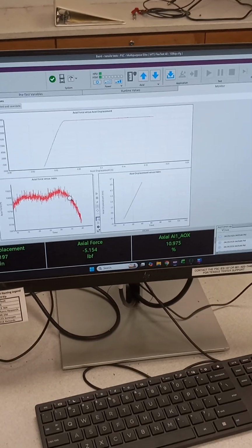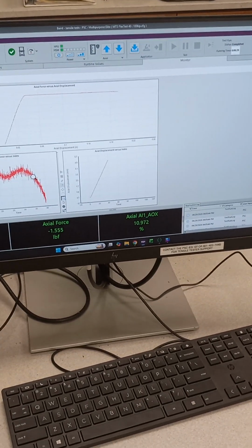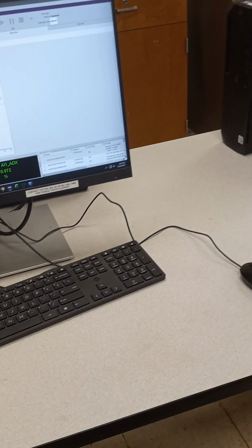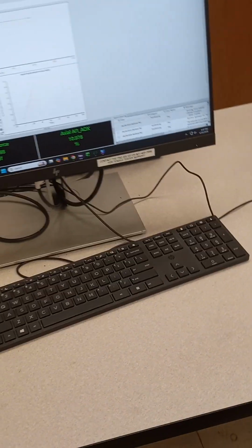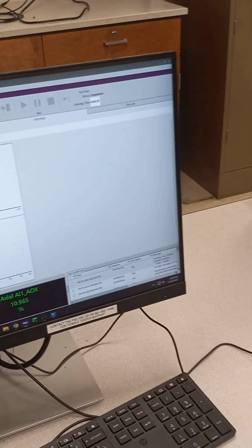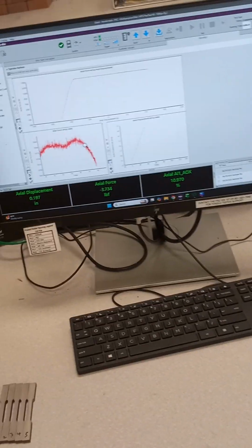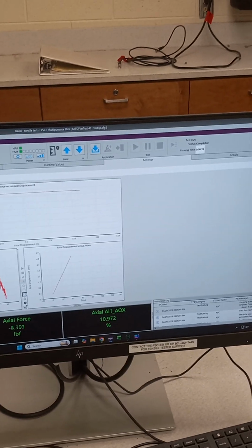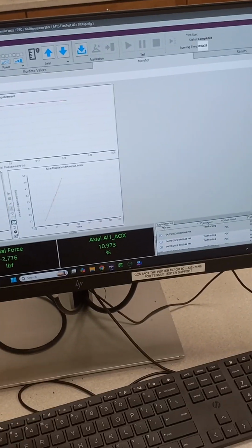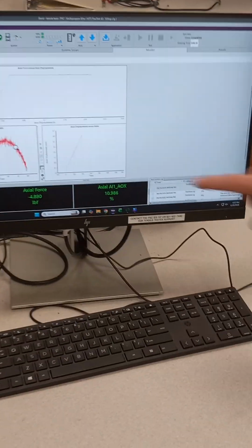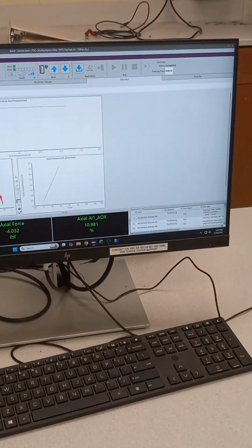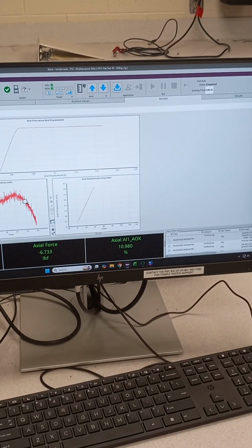So then, is there anything we need to do with the displacement? Oh wait, because this has the displacement, so we can figure out the strain from that. Would this not do anything if we didn't have the camera? Correct. So that's only there because of the camera. Yep. If this signal isn't looking good, your sample's slipping or your camera lost the marks or something, then you might as well end the test.